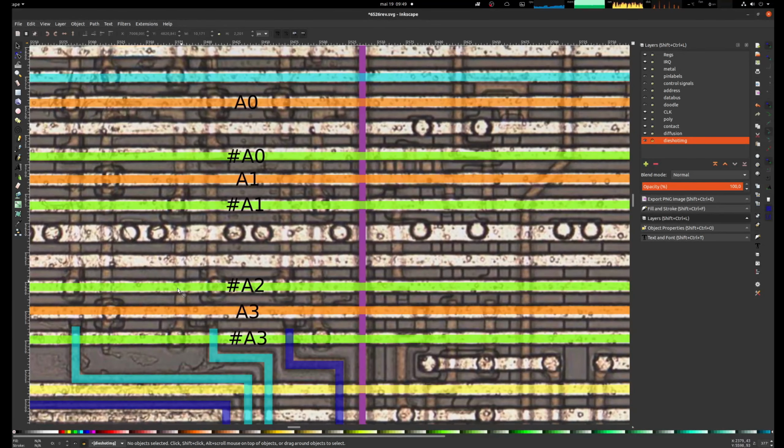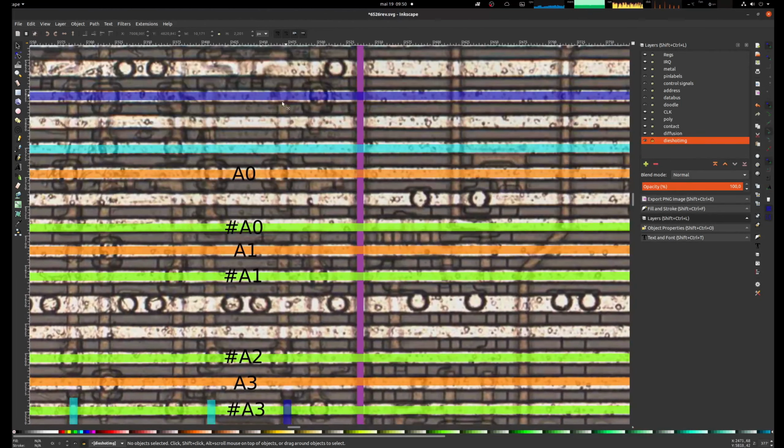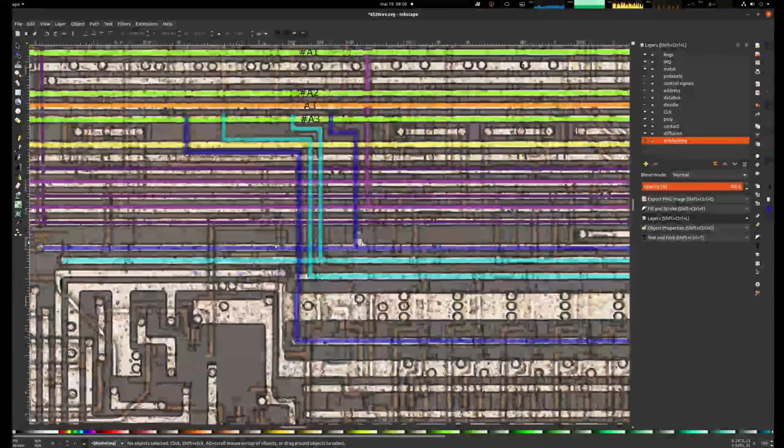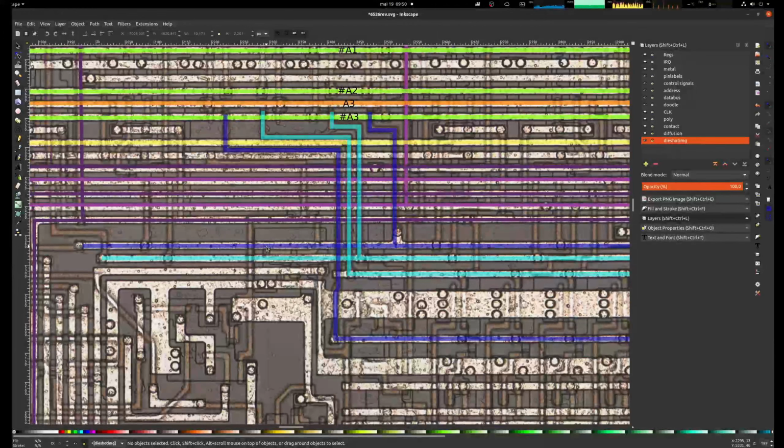But as a recap, whenever there's a negated input, you say 1, so it's the opposite. And whenever there's a non-negated input, you say 0. So here you can see the connection. So this is a 1, 1, 1, 0. So this is register E actually, and connected together with the read and write strobes. They have an output here, which then can enable either a read into the register or a write.